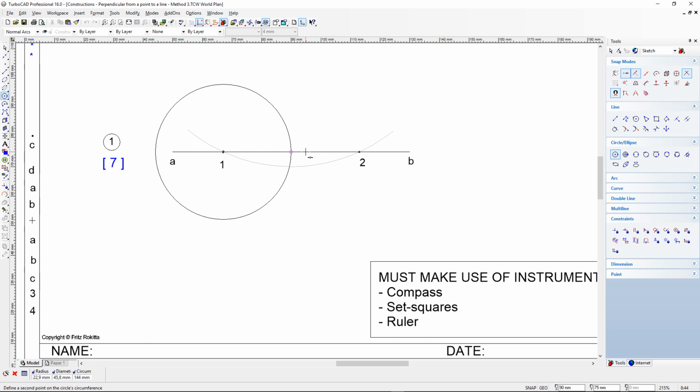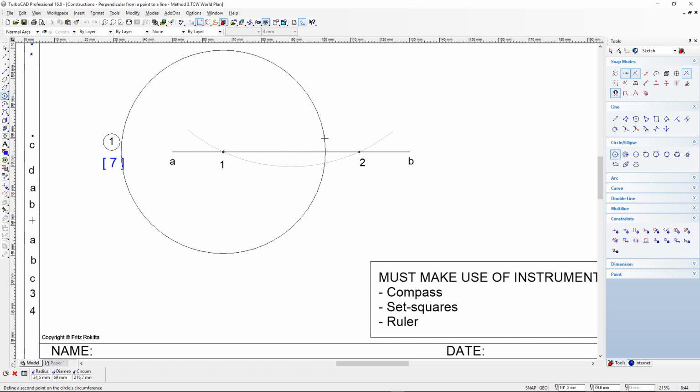As you can see here with the snap active, the radius is 22.9. That's for halfway, but if I were to cut off the construction arc here, I would not be able to get a reference point at the bottom where the two arcs intersect with one another. Therefore, I have to go more or less 3/4 of the distance, and this is just an estimation.